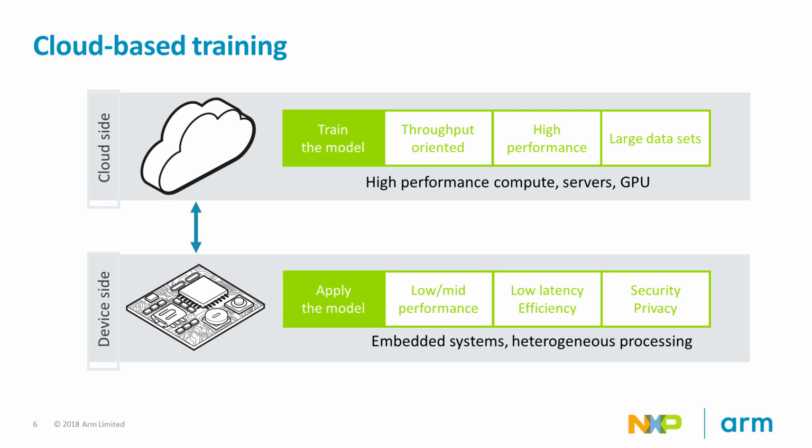While the learning process is resource-hungry and not real-time, the inference process is often real-time and low latency. It can be built to use the pre-trained model using optimized algorithms to produce just the right amount of accuracy to allow the system to respond in a safe and meaningful way to its environment. So you can see this is the first process, learning, that can be carried out offline in advance using pre-prepared data. The second process, the inference, is carried out at the edge independently of the network. And this is where the embedded bit comes in.